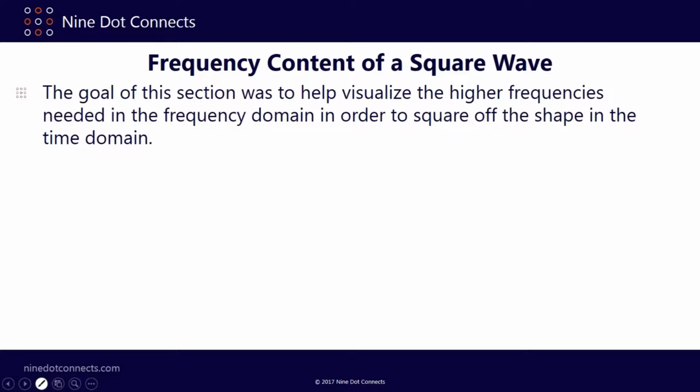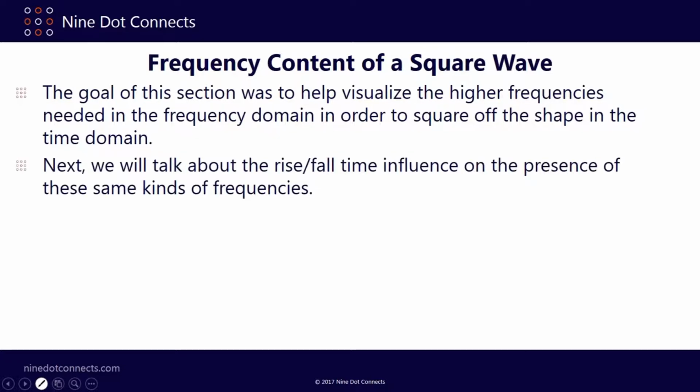Now, the goal of this section was to help you visualize the higher frequencies needed in the frequency domain in order to square off the shape in the time domain. Next, we're going to talk about the rise-fall time influence on the presence of these same kind of frequencies.